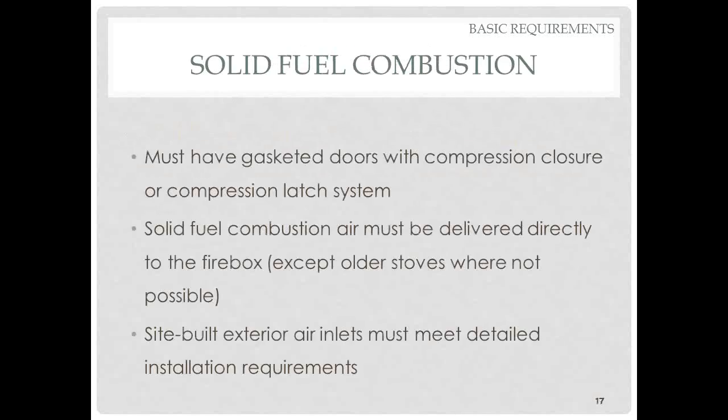For solid fuels, basically that means wood to most of us. There has to be a gasketed door with a compression closure or a compression latch system. This applies both to wood stoves and also fireplaces, both manufactured fireplaces and site-built fireplaces. Also, combustion air has to be delivered directly to the firebox, except, as the code says, older stoves where that's not possible.